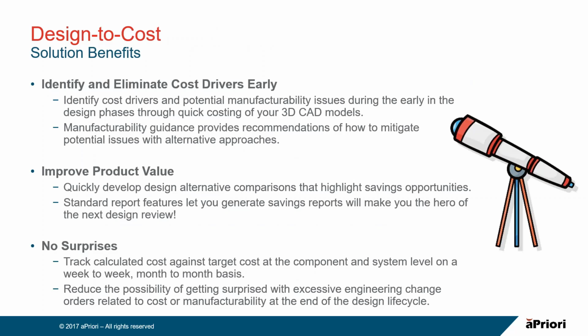So when we look at the design to cost solution benefits, it's really addressing those questions within the functional domains that we talked about. So it's the ability to identify and eliminate cost drivers early in the engineering process before anything's been manufactured. So if we can understand those potential manufacturability issues or where we may be driving cost into the product, that gives us the ability to proactively take action on it, right? Whether that's through redesign or whether that's through potentially adding critical dimensions through the manufacturing process to make sure that we have a high quality at the end. It gives us the ability to make those sorts of decisions before we've cut any metal or injected any plastic